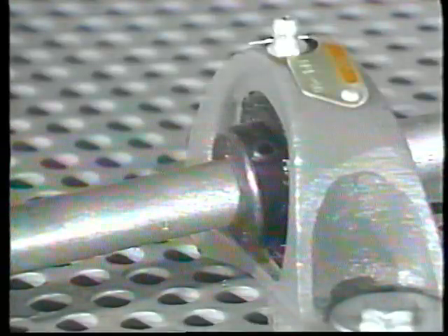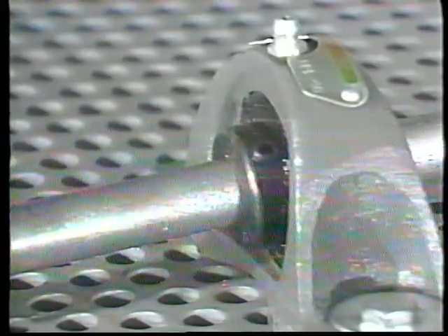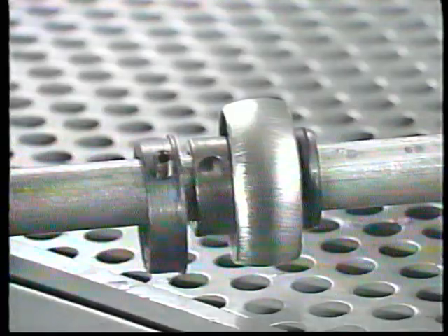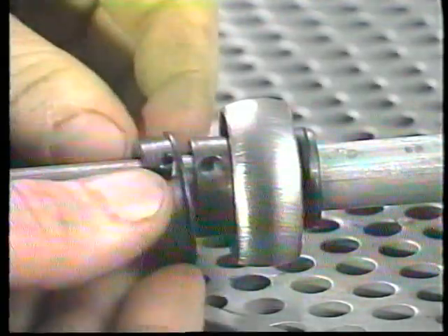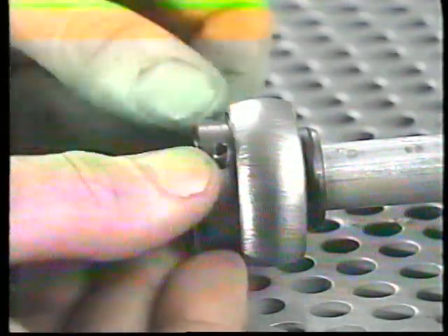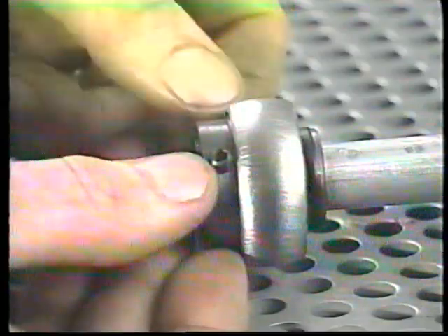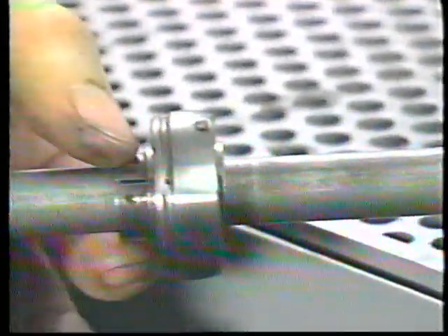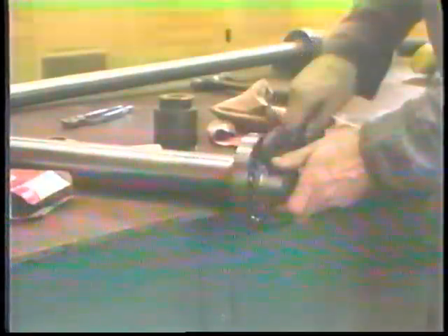Inner rings are often locked mechanically. A common method is the use of set screws connecting through an extension of the inner ring. There are various kinds of locking collars. In some, the set screws go through the inner ring to the shaft. In others, a clamp squeezes the bearing's inner ring tight on the shaft. Large bearings often use a tapered adapter sleeve, the tightness of the fit is adjustable with the nut, which forces the bearing inner ring tight on the tapered sleeve.